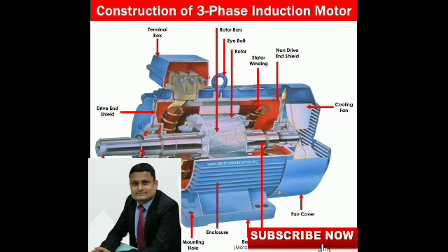Now, increasing the speed, we cannot increase the speed of the machine beyond a certain limit, because higher centrifugal forces may damage the rotating parts, and there may also be large frictional loss. So two things: high centrifugal force may damage the rotating parts and large frictional losses can occur.